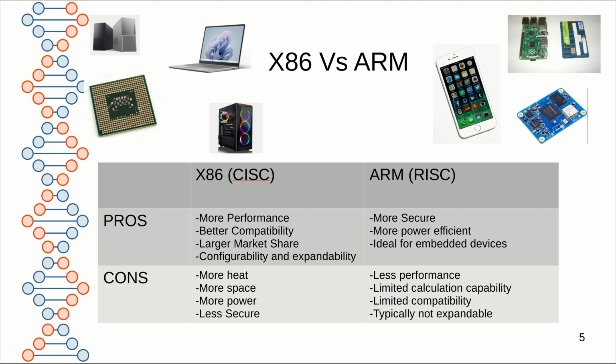Most desktop and laptop systems use a type of complex instruction set computing CPU called an x86 processor. x86 is considered part of the CISC computer chips. x86 was a standard developed by Intel in the late 70s, and it's found in most computers today, including workstations and servers, and even the fastest chip in the world currently uses x86. x86 is typically limited to advanced computing tasks, and less complex and/or lower power devices use a different implementation called ARM. ARM is often found in embedded systems or devices that are designed specifically to not use a lot of power for performance. Examples include smartphones, smart TVs, and other wearable consumer electronics.